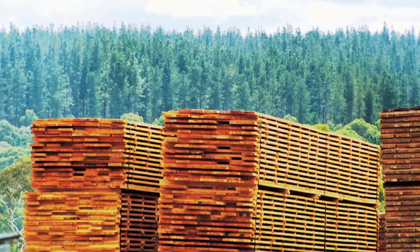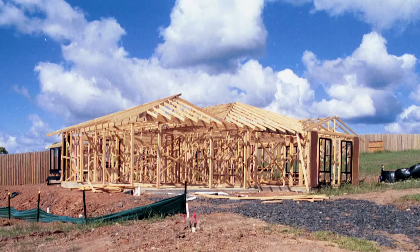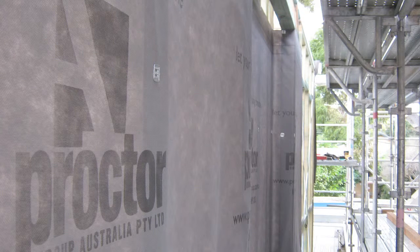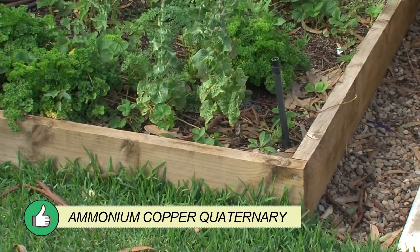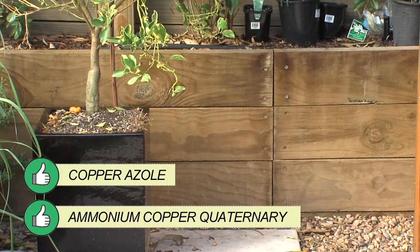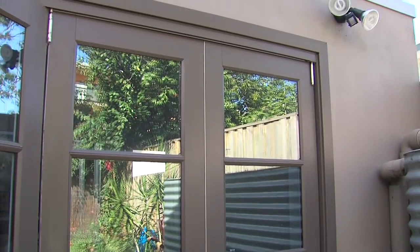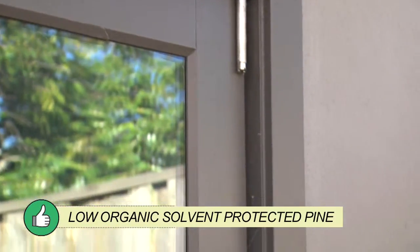Plantation pine is a good alternative to hardwood for many applications, but it's less durable and must be protected against termites and moisture. For pine framing, avoid condensation and use a breathable membrane when required. Check the moisture content of the framing before cladding. If using pine in ground, choose products treated with ACQ or copper azole. Avoid products containing arsenic and chrome, such as copper chrome arsenate. If using pine for above ground outdoor applications, such as external windows or doors, use low organic solvent protected pine.